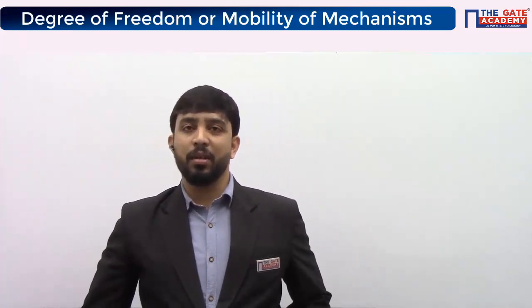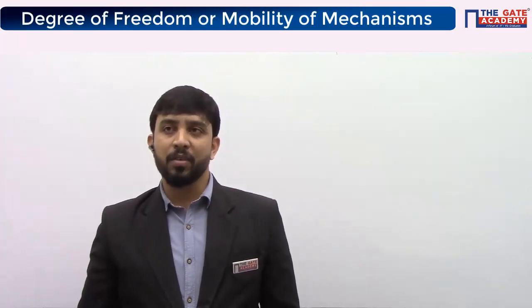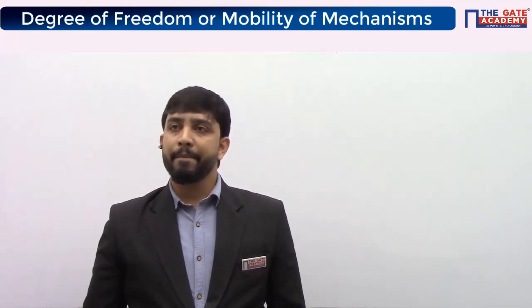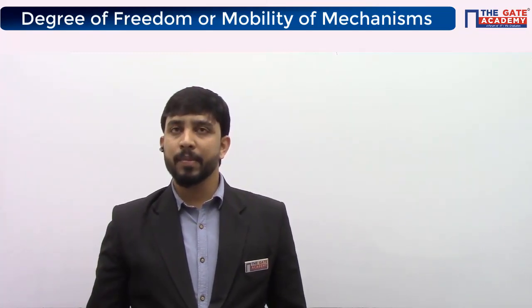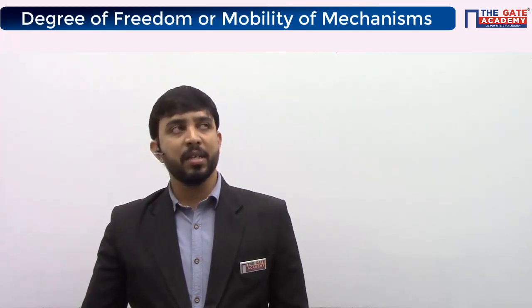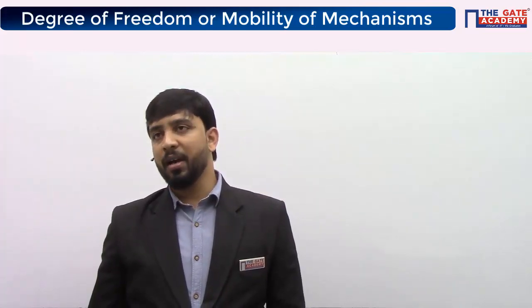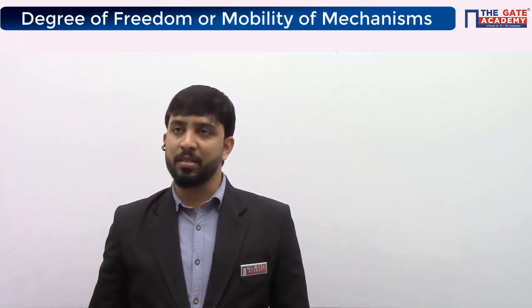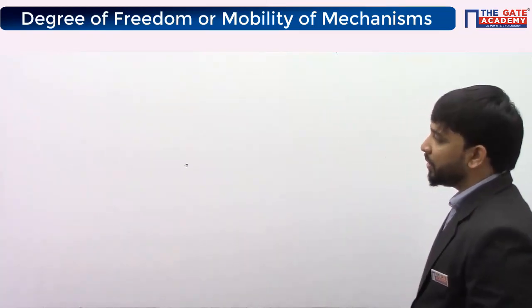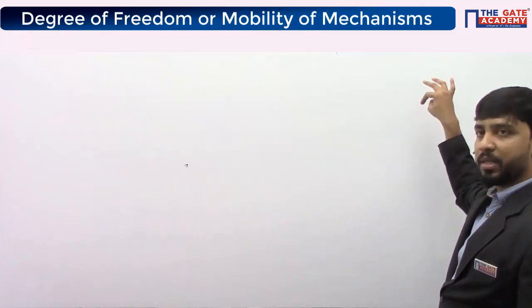Yesterday we discussed the minimum number of degrees of freedom for any kinematic chain. So what is the minimum number of degrees of freedom for a kinematic chain? I told you yesterday I can move the entire kinematic chain in x direction, I can move the entire kinematic chain in y direction, and I can rotate it about z axis. Okay? So you will be having 3 degrees of freedom, okay? So the entire chain can be moved in x direction, it can be moved in y direction, and it can be rotated about z axis.